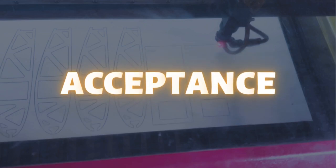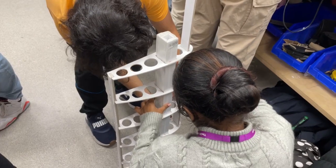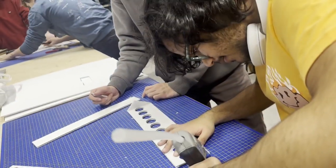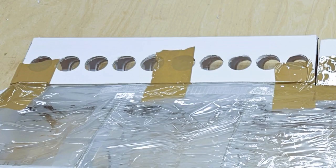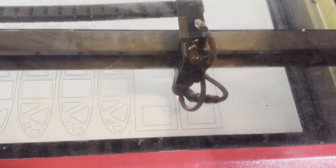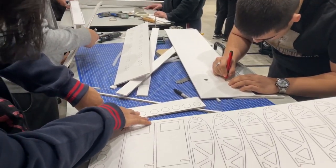We also model ribs, leading edge, trailing edge, and control surfaces along the spar, and we choose to connect the control surfaces to the wing using tape and forming a hinge. In our 4 lab sessions, we laser cut the parts from the foam board and constructed the components.